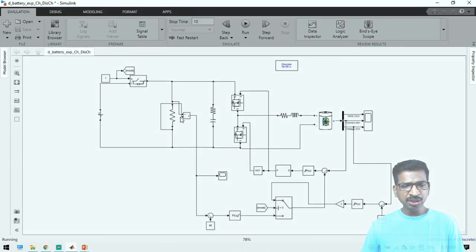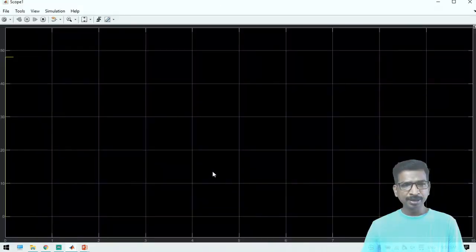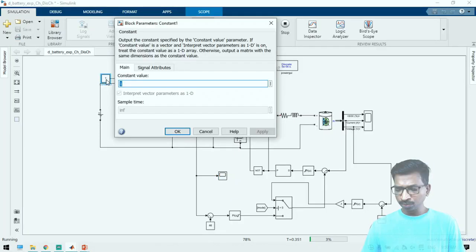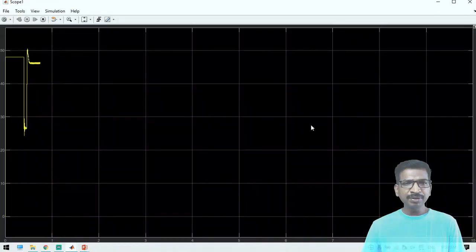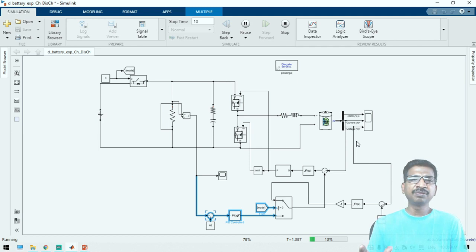So now the source is connected to the network, so the load always will receive 48 volts. Here, the 48 volts. Now I am disconnecting the source from the network. So now the battery will supply the voltage to this load. Even though the battery has only 24 volts, we need 48 volts. So for that only, this loop will take care, then compare and generate a PWM. So like that we can achieve the entire battery integration into electric vehicle systems.